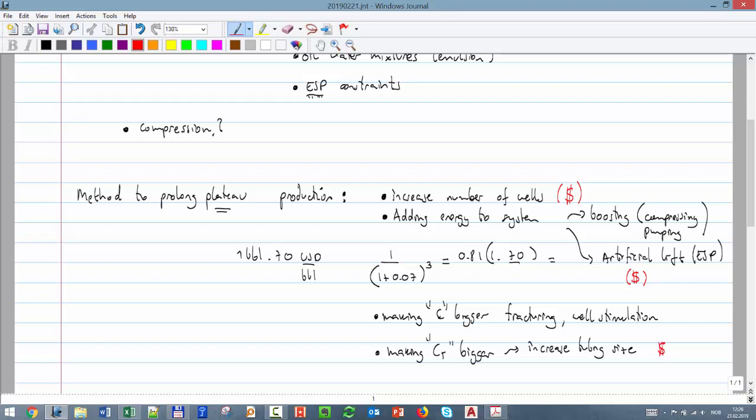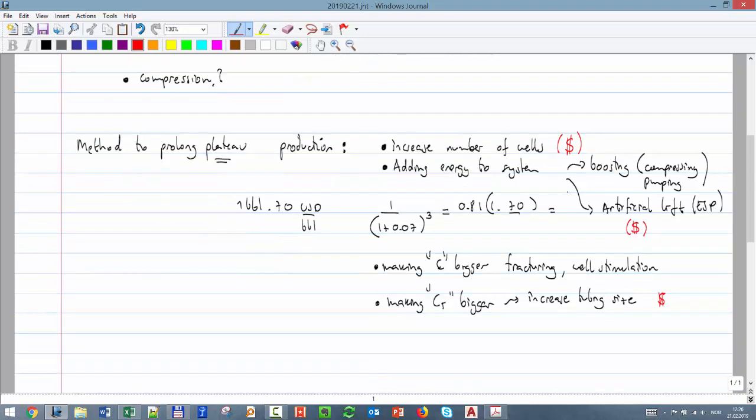Or it might be that you have some accumulation of some solids on that tubing. With time simply the pipe becomes smaller and smaller, the cross section. So you can clean the pipe. You can somehow remove the solid deposition in the tubing. The same thing could happen in the reservoir. You have some deposition, precipitation of scale, for example. You can inject some chemical just to try to make the pore space as it was originally.